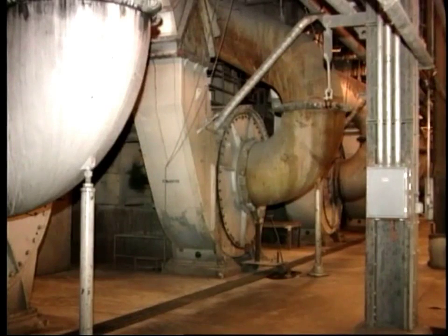In this arrangement, the exhauster fan is conveying both primary air and fine coal dust on its way to supply the burners. The result is a great deal of erosion and wear on the fan internals, requiring regular downtime for maintenance.